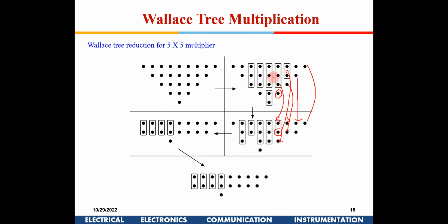Yes. Okay. Now in the next stage, I have put a full adder here. So the sum out here is here, and from here also there is one sum which is here. This one I don't have to bother about, but there is a carry which is going to come from here, that is available here. Is it okay till here? Sir, but what about this carry being generated from this full adder on top? Yes, that will be taken care of in the next stage.